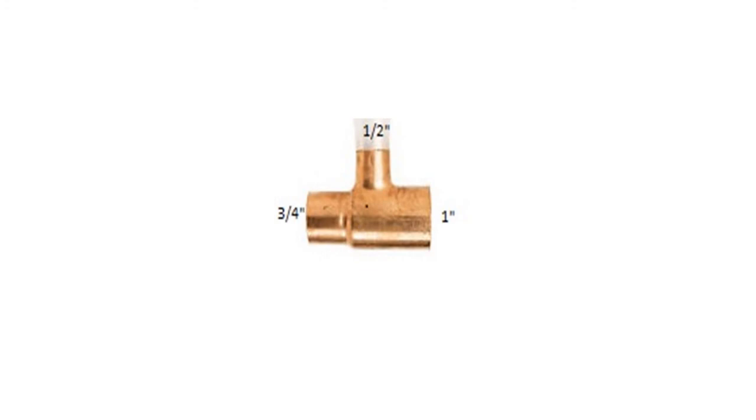T's where the run and the bowl or branch are not uniform are referred to as reducing T's. When you have a reducing T with different sizes, the way you would order it is first say the largest run, followed by the smallest run, followed by the bowl or branch size. So this reducing T would be called a 1 inch by 3/4 by 1/2 inch reducing T. If you were ordering that T, you would also have to say that it was copper. To order a T that is uniform in size, so that all the fittings are exactly the same size, and let's say they were all 3/4 inch, all you would have to say is, I want to order a 3/4 inch copper T.